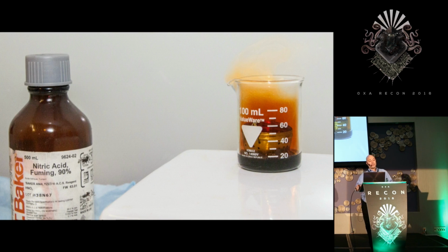To look at the chip under the microscope, I have to decapsulate it. So I use fuming nitric acid for this. The chip is immersed in heated red fuming nitric acid. This reacts with the plastic packaging and removes it. The chip is then rinsed in acetone and cleaned with isopropyl alcohol in an ultrasonic bath, and then you have a nice, clean, bare die. The nitric acid is aggressive, and it's important to handle it carefully, but the process really is very straightforward. Most people wouldn't want to do this inside their home, so use the fume hood you have set up in your garage.